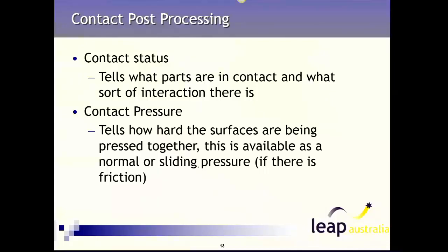If you have a bonded contact and you look at the contact pressure, and there's a large area of negative contact pressure and it's not welded or glued together, then it's likely that those parts are trying to separate, but you're not allowing them to because you've got a bonded contact. You can rerun the model by splitting the area up so that only the positive pressures are in contact. Although you're running a linear model, you'd have to do that multiple times until you iterate towards a solution where you've only got positive contact pressures. So it's much easier just to switch to a non-linear contact and let the contact take care of that for you, putting just the positive contact pressures into contact.